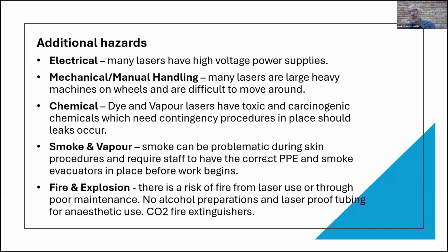And so you have to have the laser-proof tubing when you're doing work like that with lasers, and your fire extinguisher. The modern rule now is to get all these foam and powders and stuff. Let me tell you, they all fail at 1,000 volts. And with your high voltage laser, it's not going to work. The only extinguisher that's going to work on your laser when it's on fire is a CO2 extinguisher. And that's because it's a gas that starves that fire of oxygen and puts it out. And so just remember that.